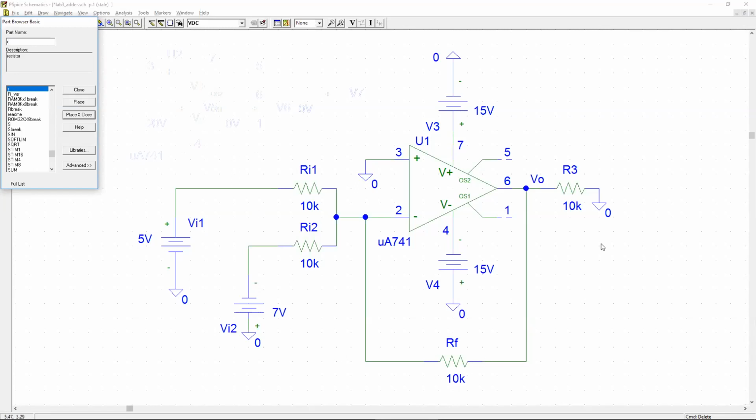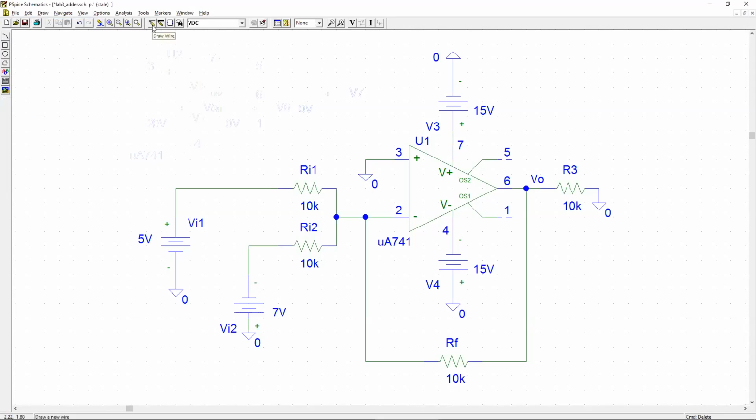And for the ground, if you write GND and then choose ground analog, this one is it. I think I have mentioned all the components. After placing them, if you want to connect, you can use this symbol, which draws a wire. Drawing this circuit should be easy for you as you have already done two experiments related to this. So let's move on.